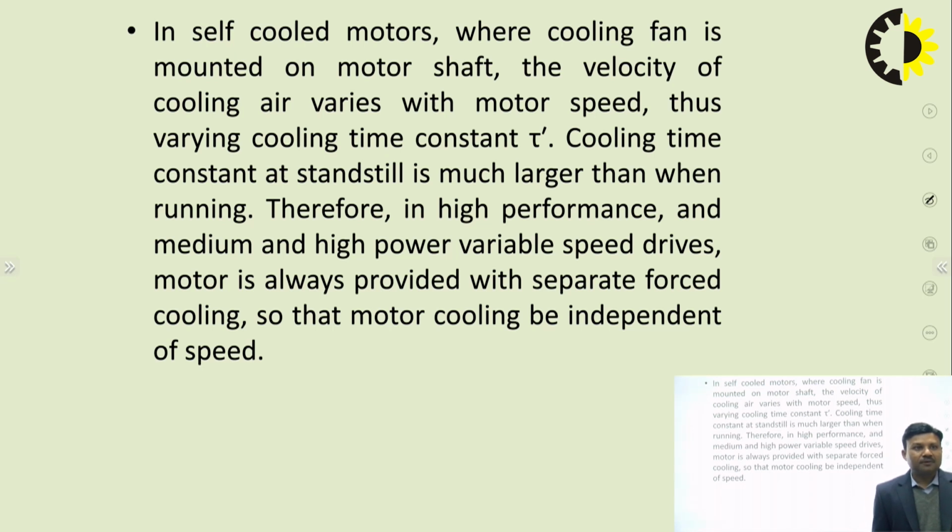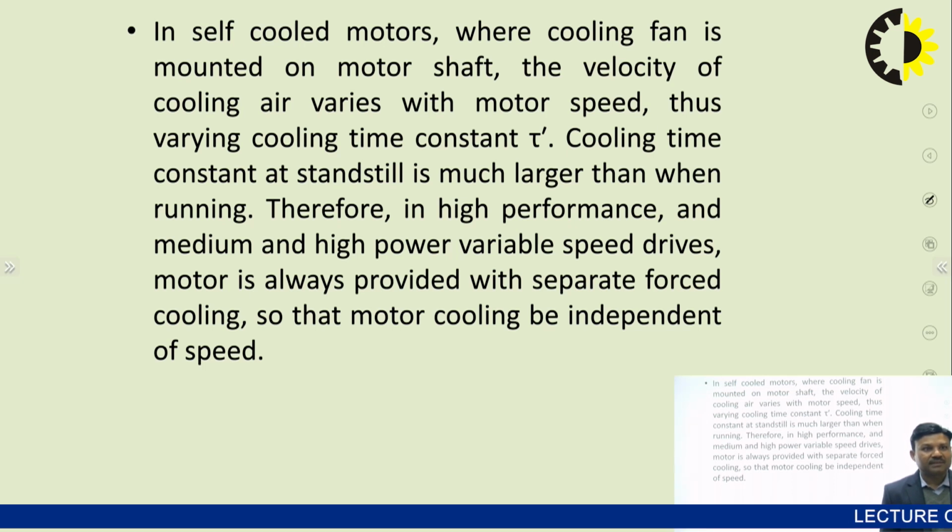Therefore, in high performance and medium and high power variable speed drives, the motor is always provided with separate forced cooling so that motor cooling is independent of speed.